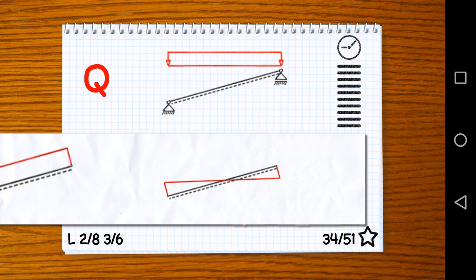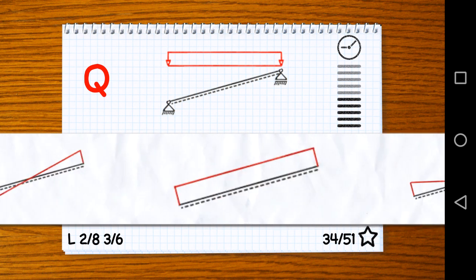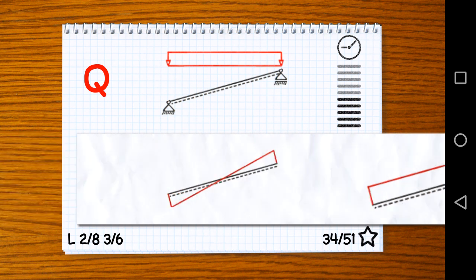Looking at this element from the right to the left, we should have a linear distribution going downward in the direction of the distributed load. That's a trick we've explained already. So this one is wrong because looking at this distribution, the right answer here is wrong. Looking at this distribution from the right to the left, we're going upward. That's wrong. This one is wrong because it's constant. So here's the correct one.